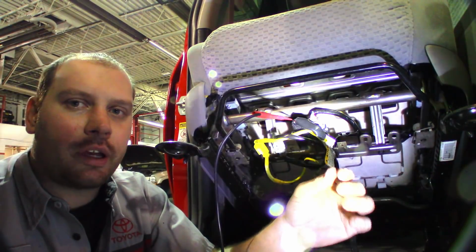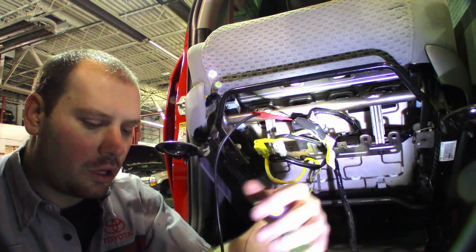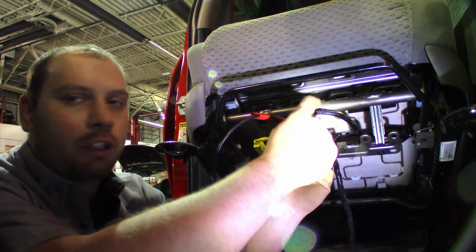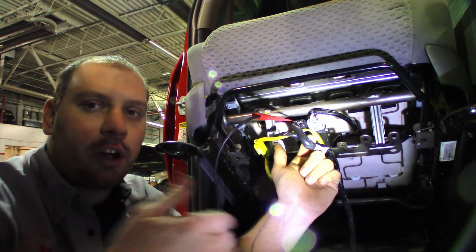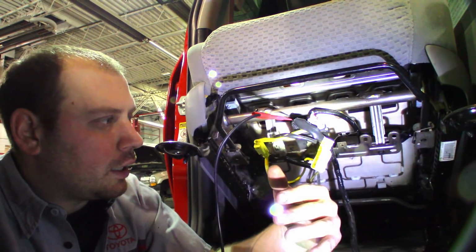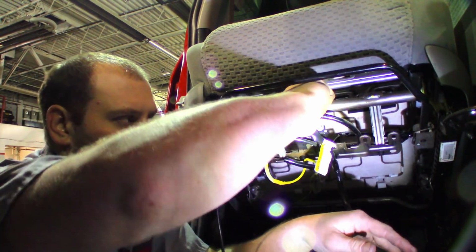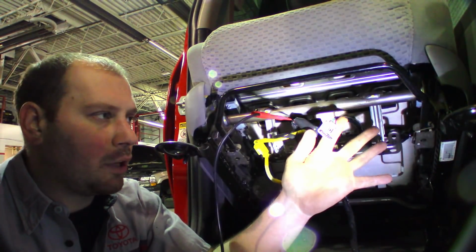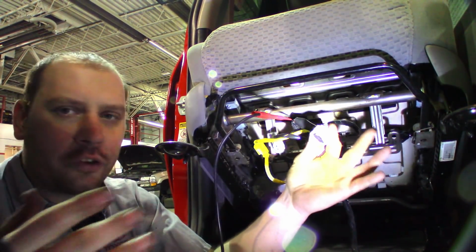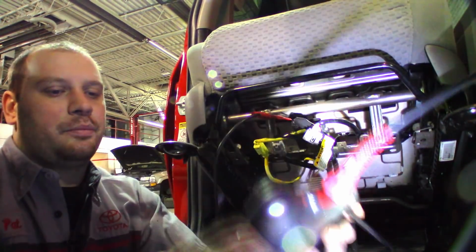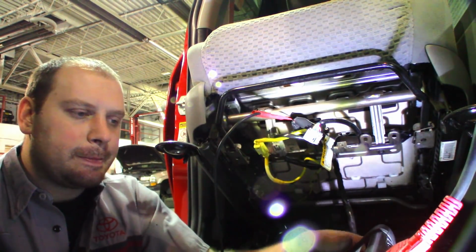The last thing left to check is my 5-volt references. Now, this actually does have 5-volt references. It goes to all the weight sensors, but it's all in this white connector. So if I unplug this white connector and there's any issue with the 5-volt reference, this should clear it up. I think there's four 5-volt references in it. I'm going to disconnect it and try to communicate one more time. I don't know if you can see that. Still no communication.